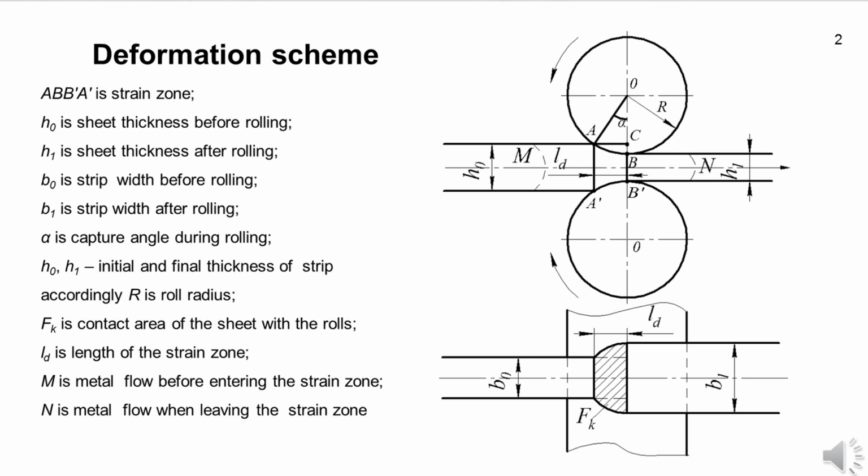The ability to plastic deformation of metals and alloys is determined by the yield strength of the material, which also depends on its internal structure. We therefore investigated regularities of the influence of the amount of reduction during cold rolling on grain size and grain boundaries. This will allow adjusting the strength and ductility of products by controlling the value of compression during cold rolling of steel.